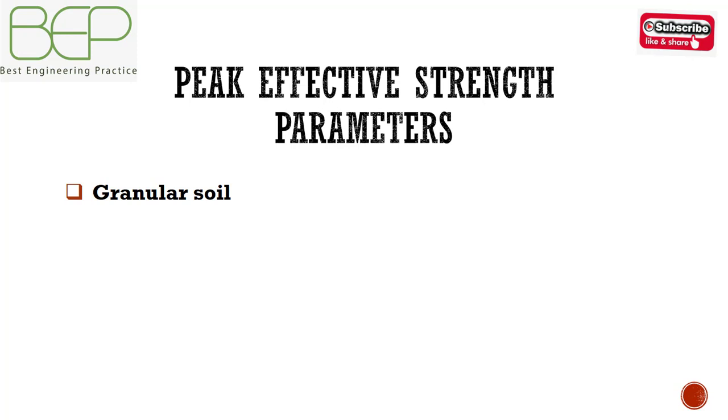Granular soil. The effective strength parameters of a granular soil are a function of particle size distribution, soil density, imposed stress level, angularity, and cementation.